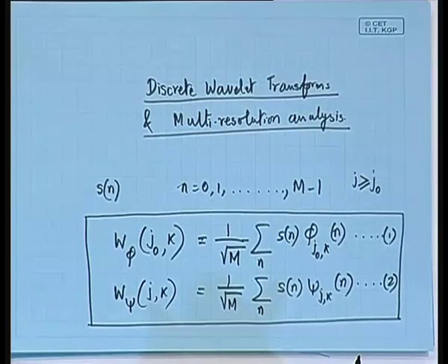So, to maintain that, either in the forward transformation we have to apply a coefficient of 1 by m, and in the inverse transformation we apply a coefficient of unity, or otherwise an alternative form of doing it is to have in the direct transformation a coefficient of 1 by root m, and in the inverse transformation also have a coefficient of 1 by root m.